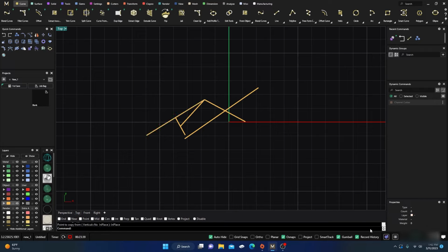Okay. Super select. That's this here. So with super select, you can select all your curves. You can go through there, select all open curves. There's all kinds of options you have, but the best one here is select duplicate objects. And if I select duplicate objects, you can see it chooses those two duplicate objects that I have out there, and I can just delete them. And now duplicate objects will not be, oh, there's maybe, yeah, they're still okay.